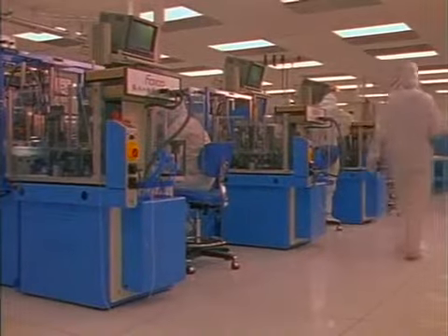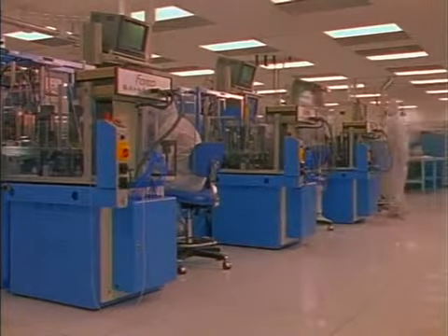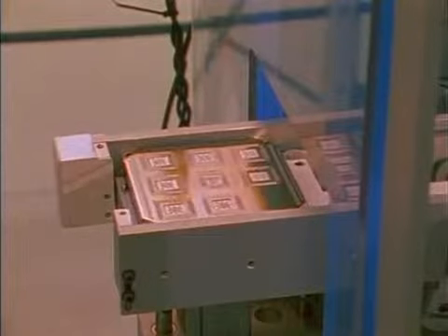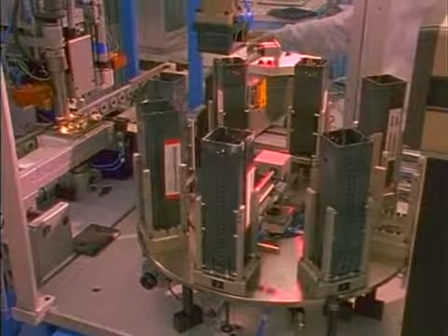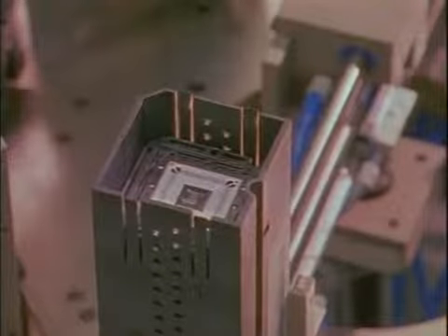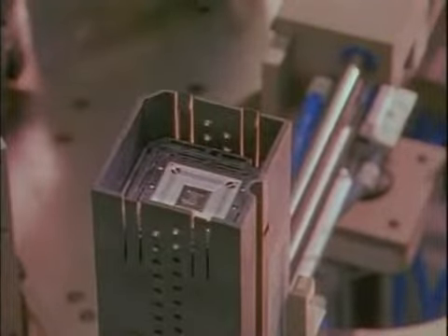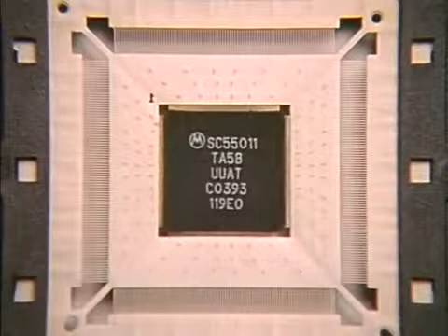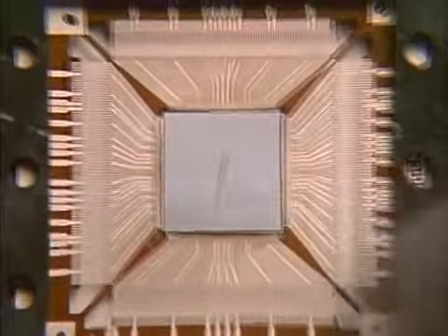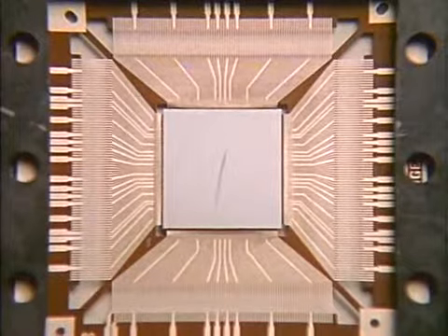In die bonding, this manufacturing facility uses 3 separate machines to accommodate the 3 sizes of fast chips used in the multi-chip units. The die are bonded to the high-density signal carriers using a chip-to-substrate interconnect called tape automated bonding, or TAB. This TAB chip is densely packed with leads on all 4 of its sides. From the back, we see the inner leads fan out to the outer leads where the bonding will occur.